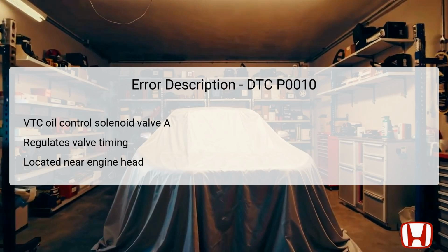A failure in this component can lead to poor performance, reduced fuel efficiency, rough idling, and in some cases, increased emissions. It's essential to understand that the solenoid receives commands from the engine control module, ECM, which monitors a variety of engine parameters to determine the optimal valve timing.